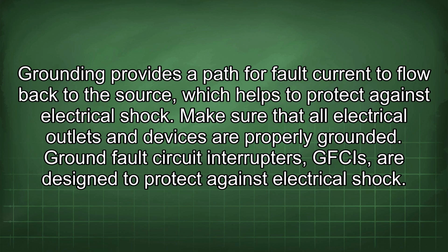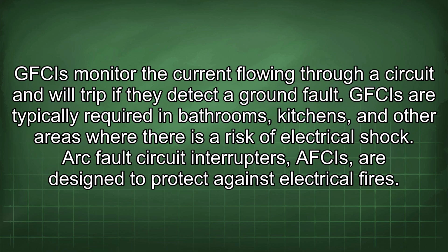Ground fault circuit interrupters (GFCIs) are designed to protect against electrical shock. GFCIs monitor the current flowing through a circuit and will trip if they detect a ground fault. GFCIs are typically required in bathrooms, kitchens, and other areas where there is a risk of electrical shock.